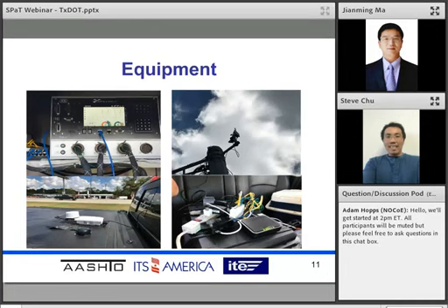And this is what one of the vendors' equipment looks like. Basically, we swap out the controller. It's an Intel controller. We swap out the controller, and then after that, we install the DSRC radio. For this system, it goes straight from the controller to the radio, and from there, it broadcasts the SPaT messaging. And then we have a test truck, and the truck mounting outside is an OBU that's receiving it.